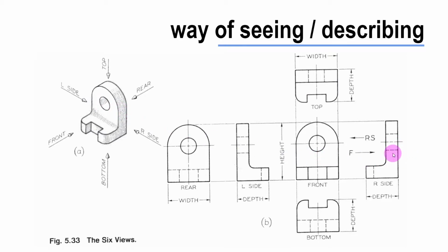Same thing then in the side view. If I'm looking directly at the side, I can't see the slot that's back here through the middle. And that's why the back edge of it is this hidden line, to show that that's how far back that slot goes. And the same thing then with the hole that's going through that back face.